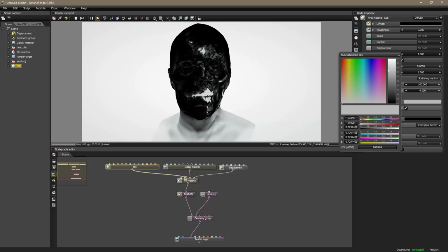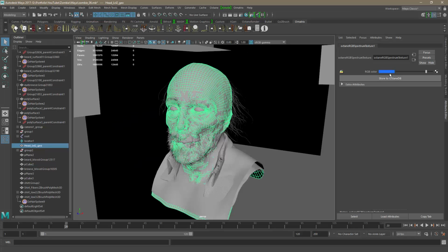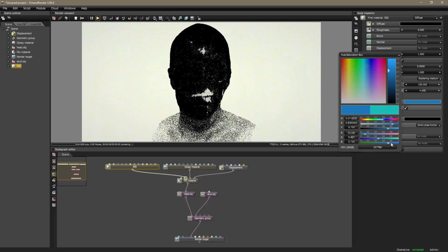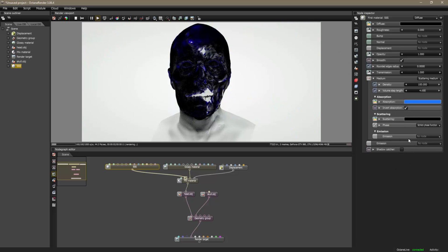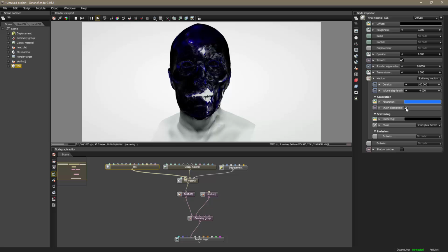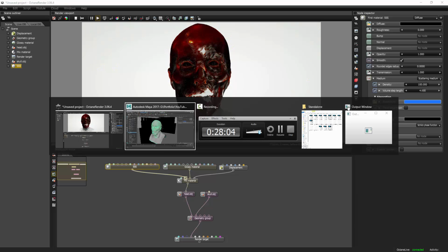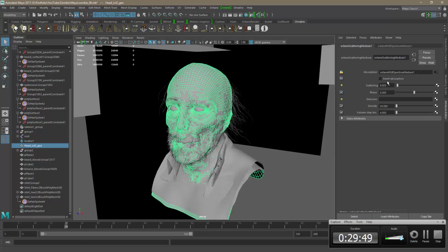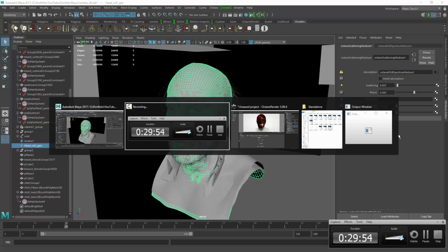RGB is going to be this value, then G is going to be this value here, and this value is going to be 1. So hopefully we got the same color, and it looks like it. Uncheck invert absorption, and let's see what other parameters we had. Let's go back here. Scattering was 0.025 and density was 50. So let's do the same.